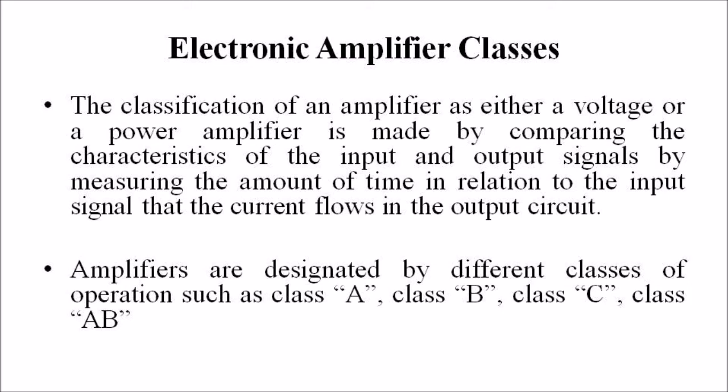This small base bias voltage added to the input signal allows the transistor to reproduce the full input waveform at its output with no loss of signal. However, by altering the position of this bias voltage, it is possible to operate an amplifier in a mode other than that of full wave reproduction.